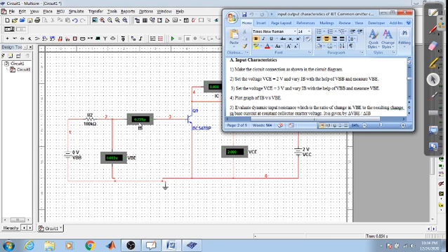The source of current is this voltage, so you need to vary this voltage, and when you vary it there will be some current entering here and some voltage existing across base and emitter, which is called the VBE junction voltage. So when you vary this VBB, the current IB and voltage VBE will be shown.